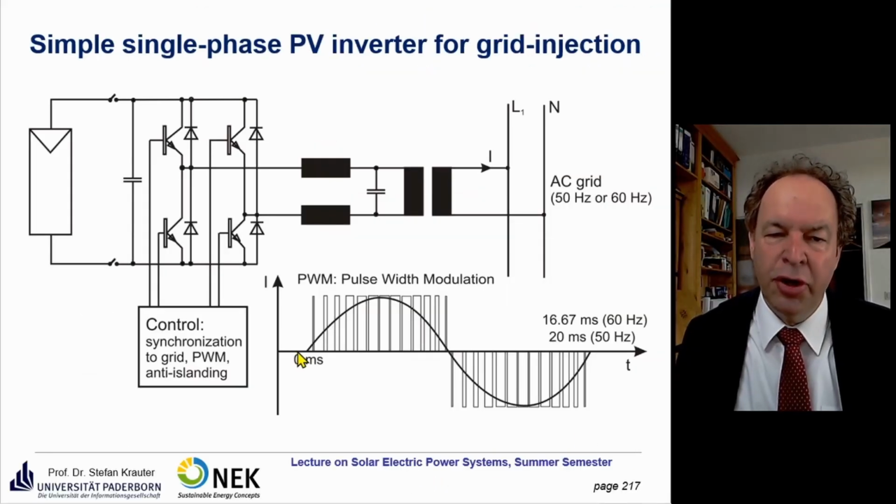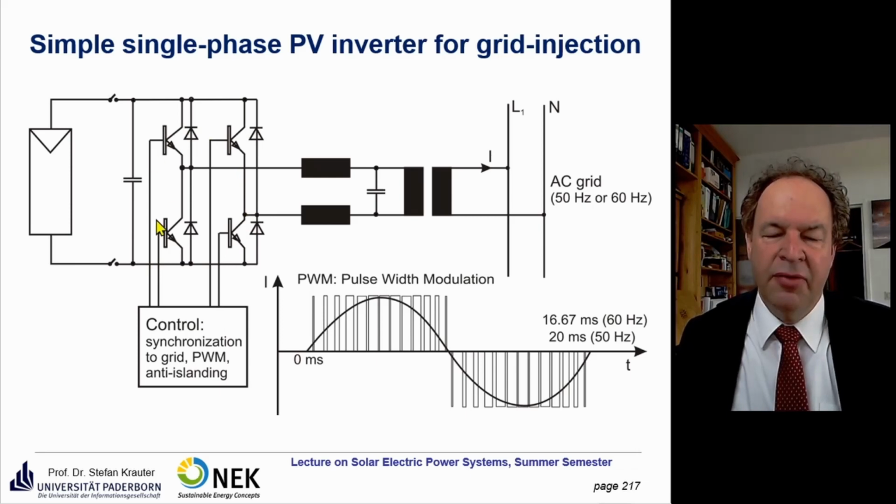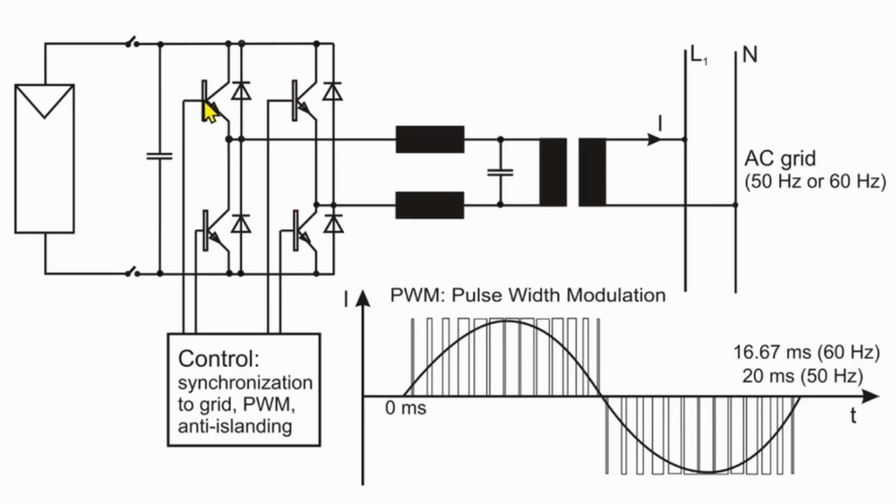Very simple inverter, a 4-pulse inverter. So you have here 4 switches, for example, thyristors or triacs or GTOs or IGBTs or even MOSFETs, controlled here by the gate. And this control is made in such a way that you have either that or that in conducting operation, otherwise you would create a short circuit. If you put this here, then you would have positive voltage on that part of the circuit. So you put this on a negative part, so ignite this and that. You can create pulses by that.